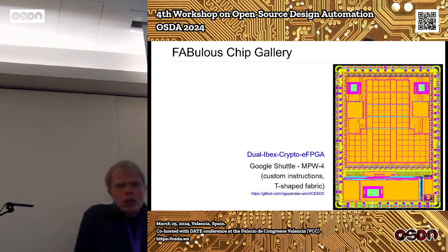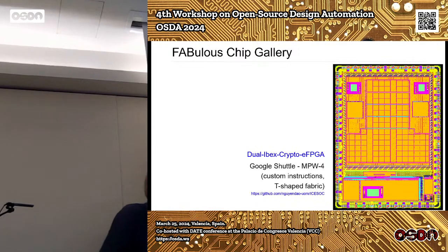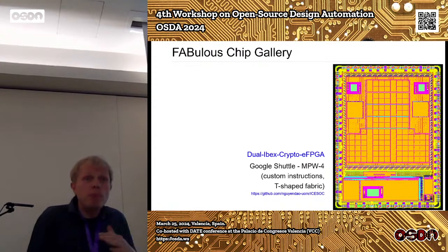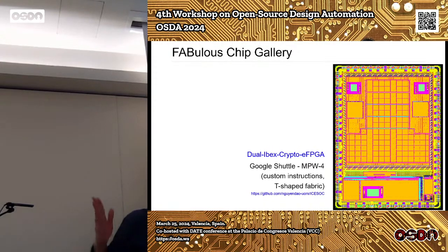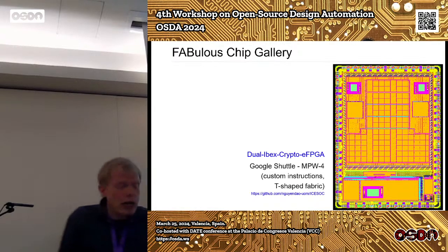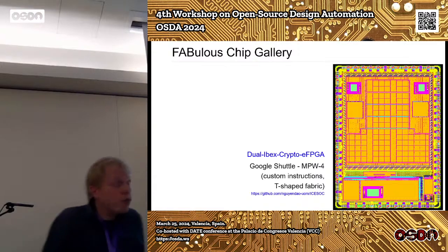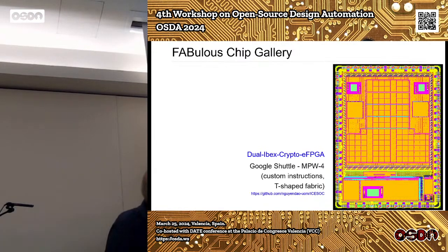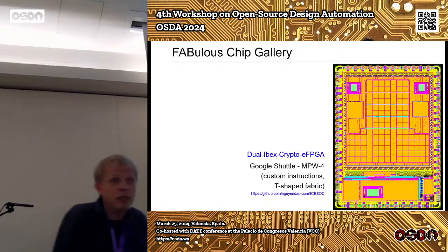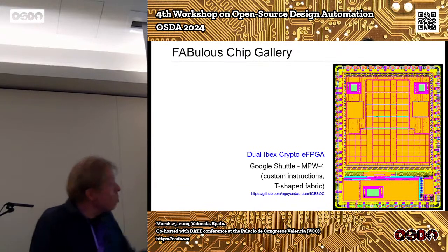Another chip that we did that we couldn't bring up so far is a dual RISC-V system. What you see in this chip photograph at the top is that we take the operands that usually go from the fabric back into the register, and we use some of the instruction formats dedicated for custom instructions, so RISC-V cores can work simultaneously. Unfortunately, there are hold time violations in this infrastructure, which is not a problem of the fabric, but it prevents us from bringing it up in full beauty.